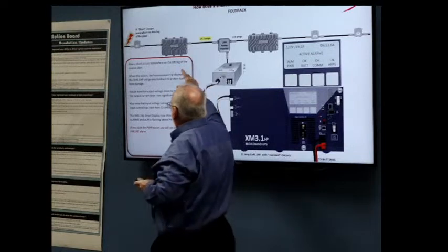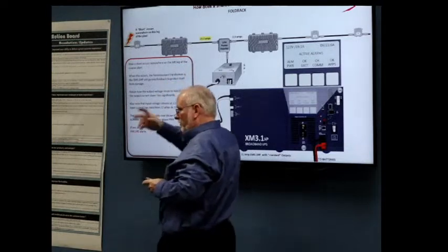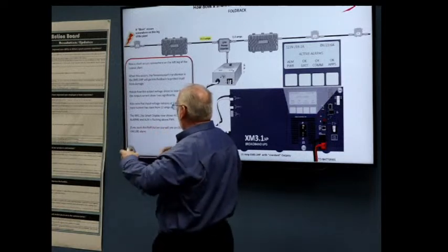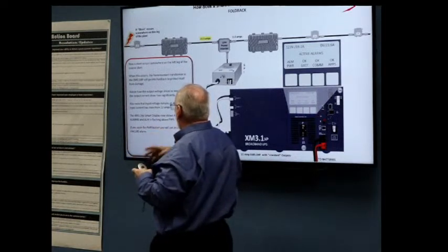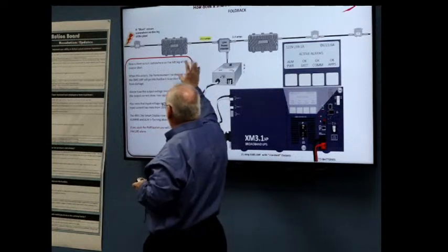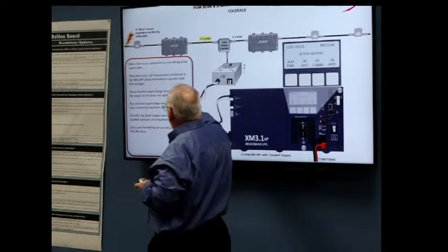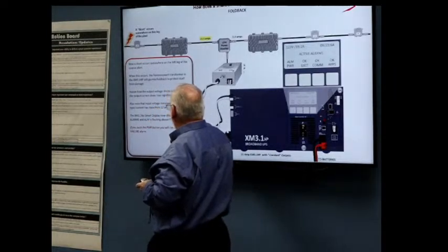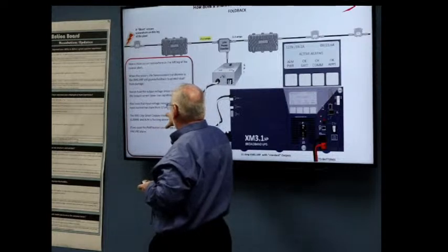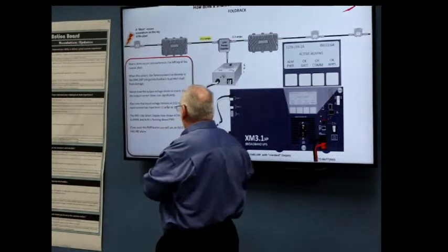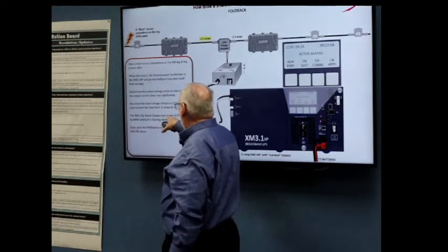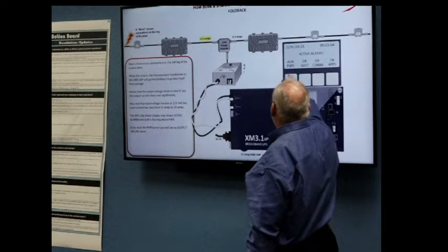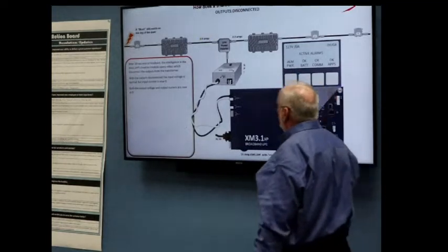Okay? The ferroresonant transformer will fold back. Physically, it goes into a state where it's just dissipating the current and running, but it's not delivering any power. The power drops to 0, but the output current rises significantly. The output remains at 123, but it actually increases to try to provide all that power. The HFC Smart Display shows active alarms, so you'll see that there will be a power alarm on the unit.